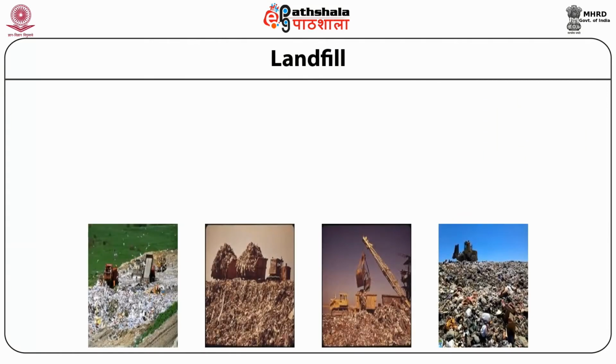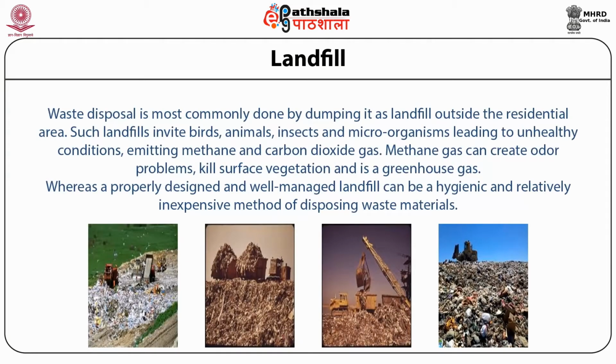The second method is landfill. Waste disposal is most commonly done by dumping it as landfill outside the residential area. Such landfills invite birds, animals, insects, and microorganisms, leading to unhealthy conditions, emitting methane and carbon dioxide gas. Methane gas can create odor problems, kill surface vegetation, and is a greenhouse gas. Whereas a properly designed and well-managed landfill can be a hygienic and relatively inexpensive method of disposing of waste materials.